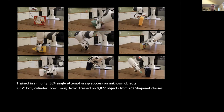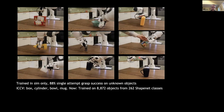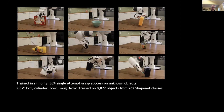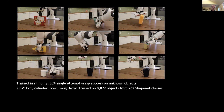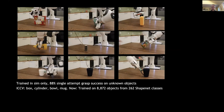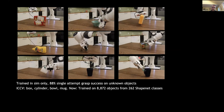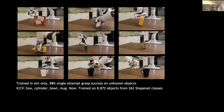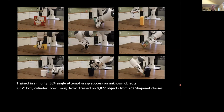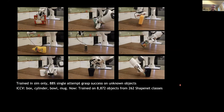Here are some examples on objects that we put individually on the robot. Two interesting points here: first of all, the system is solely trained in simulation at this point. It has never seen a real object, so it's only using depth camera data. Another interesting point is it has never seen objects with exactly that shape, so it's been trained on different objects. In the most recent instance, we trained a single network on more than 8,000 objects from 262 ShapeNet classes, and it works pretty well.